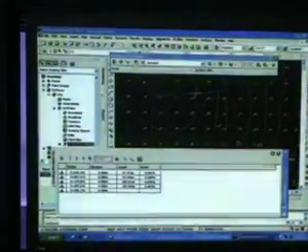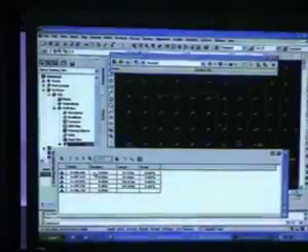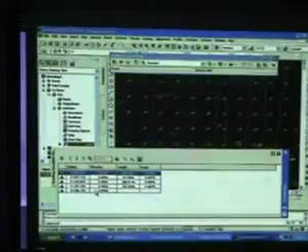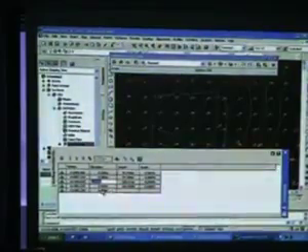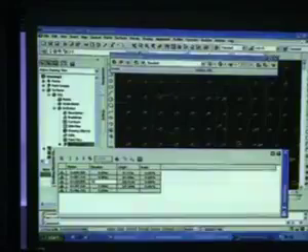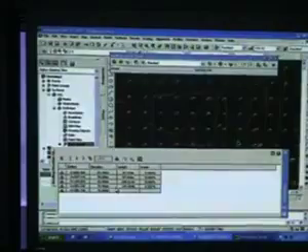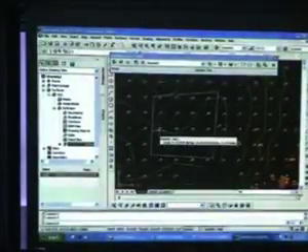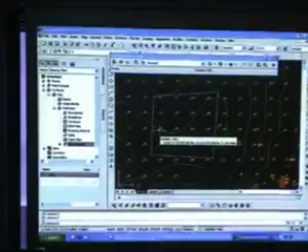A window will appear, and this is where you modify your elevation. Let's say we want to make this a flat platform. I'm going to click the first line, hold shift, and select all the way down to the last line. To modify the elevation all in one go, you click anywhere inside the elevation. You see everything else has been grayed out. Then you type in here, let's say 35 meters, hit enter, and all the elevations have been switched. Then we click the check mark to dismiss this. So now we've got a feature line at 35 meters in this drawing.